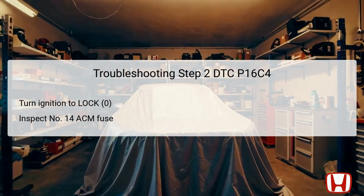After completing the first step, it's essential to turn the ignition switch to the lock 0 position to ensure safety while performing subsequent checks. The next step is to inspect the number 14 ACM fuse, specifically a 10 amp fuse located in the driver's under-dash fuse/relay box. This fuse is critical for the functionality of the active control engine mount system, and a blown fuse could directly contribute to the DTC P16C4 error.